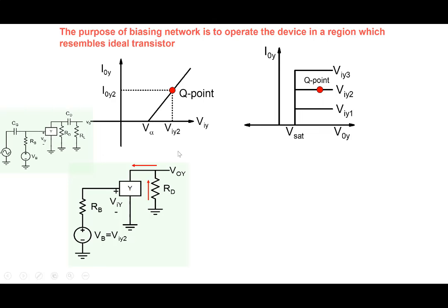here. So note that if we are to use a device like device Y to work as an amplifier, we'll have to, so this is fine, if we are applying a voltage more than the threshold point. So from the input side is okay. From the output side, we'll have to maintain this voltage as positive. Note that voltage has to be larger than VSAT, some positive voltage here, let's say 1 volt or 2 volt or something like that here. So we'll have to maintain positive, and this arrangement doesn't allow us to have this particular voltage positive.